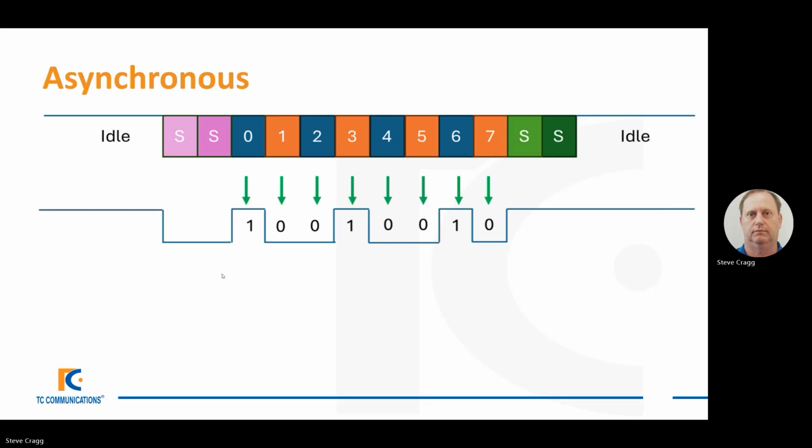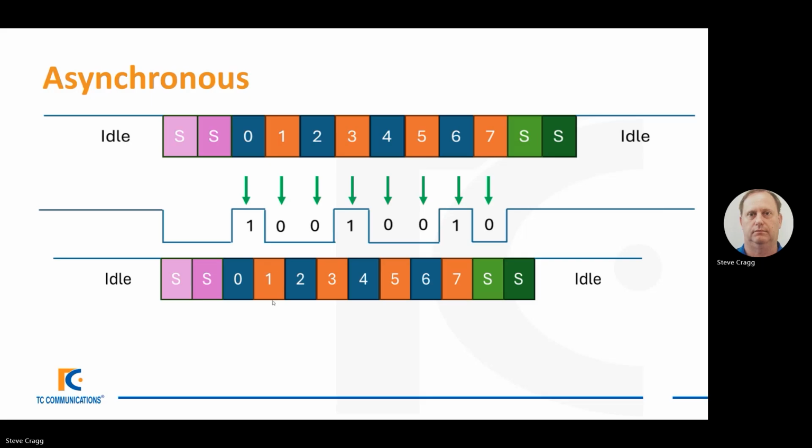So the data that was sent here is 10010010, and then when you're looking at receiving, the receiving device thinks that the data should have been sent faster than it actually was. And you can see here that it's thinking that it would have received the data by the end of, not even the end of the first stop bit.